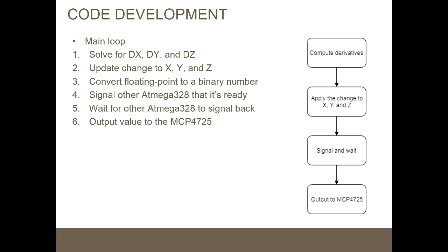So if I'm multiplying 25 bits by another 25 bits, then the most I will ever do is 25 shifts, but like 30 cycles of operation, depending on how the algorithm goes when it reads the number. With the looping case, 2 to the 25 is the worst case scenario. Whatever that big number is, it's just not good for the low profile microcontroller that I have. So the best choice was to take the time and learn the algorithm and implement it, and it will definitely work for the Atmega.